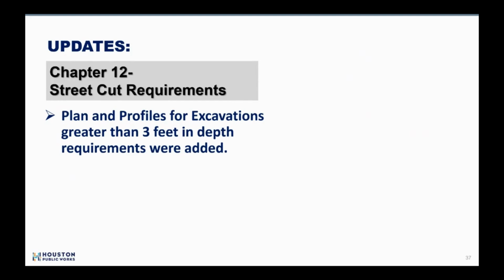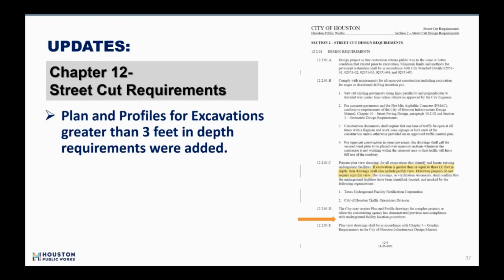In Chapter 12 for street cut requirements, again, due to the increased instances of third-party damage to the city underground infrastructure, requirements for plan and profile for excavation greater than or equal to 3 feet in depth were added.